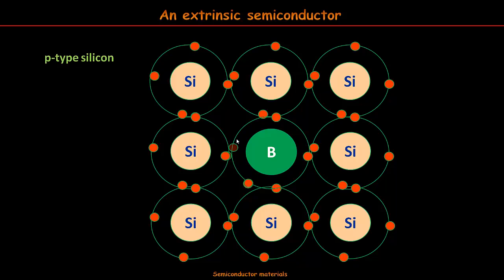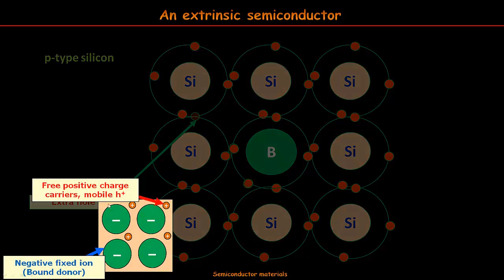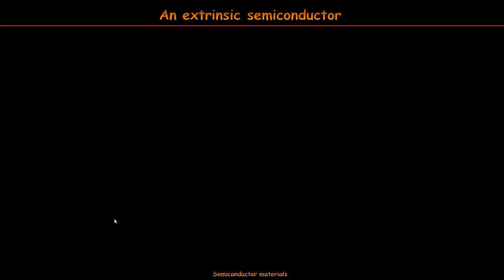Then we can assume that the P-type semiconductor consists of a semiconductor network where free charge carrier pairs are continually generated by temperature, not interesting; this is represented by the orange layer here. A set of free holes with no associated electron, free charge carriers that can conduct an electrical positive current. Here it is. And a set of the same number of negative ions anchored to the semiconductor network.